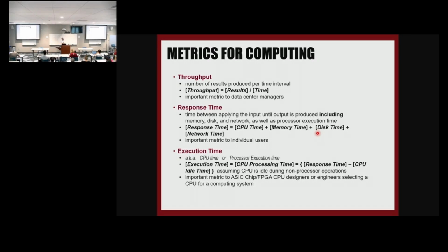So what would happen was you design a processor, you send it to space, and then because of the radiation, the transistors stop working. It's called a hard fault, right? You have soft error and hard error. Hard error is when the transistor is completely ruined, so you can't do processing. Soft error is just when you have a memory and the radiation attacks the memory and it flips the bits. So you have 0, it flips to 1, and so on.